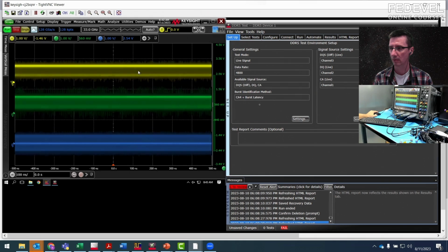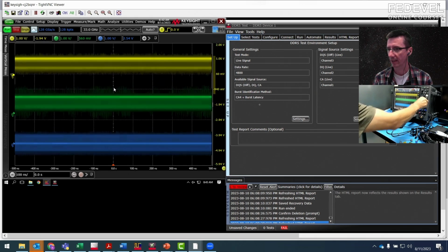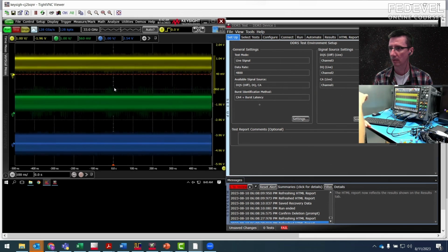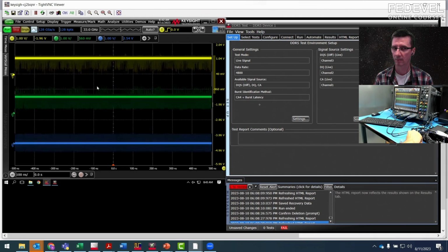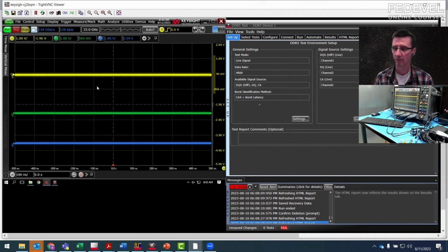Do you see how the signals look right now? Yes. They're very uniform. It's a kind of solid color. Yeah, we have a couple of outliers where the signal's overshooting. There are some reflections here, like the signal's exceeding the main level. But for the most part, it's uniform. Now I'm going to turn off the system, and let's watch what the signal looks like as the system boots up and starts initializing and going through the training.